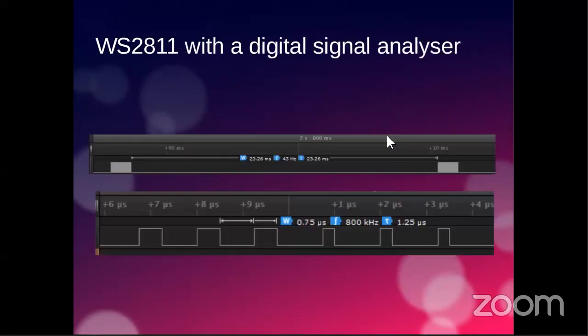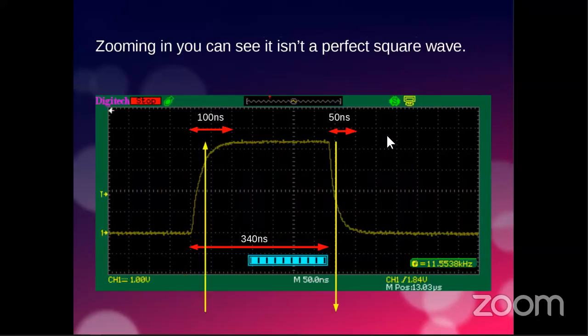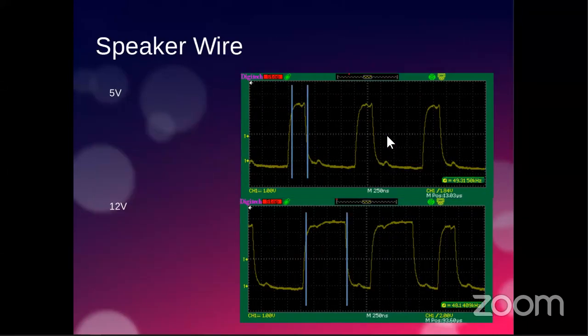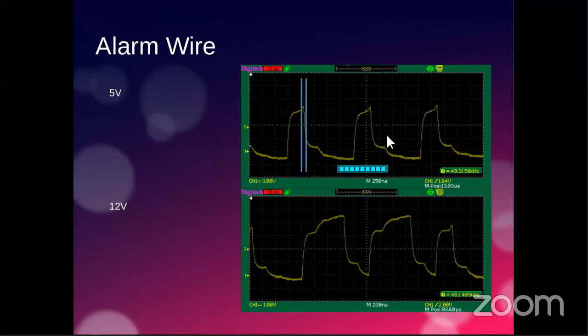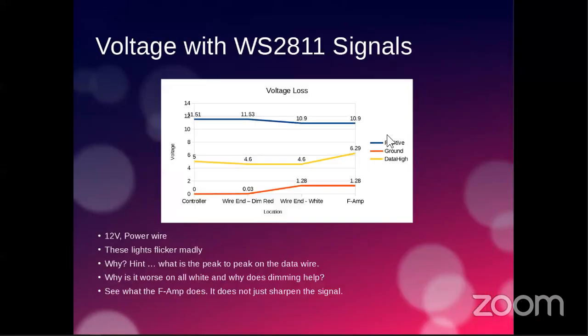if I can find it again. It's a problem with slide builds. There it is. When you do power injection, what you're doing is you're dragging the blue line up and probably the orange line down. You're not changing the yellow line at all. Okay. But by dragging the orange line down, you're increasing the difference between the yellow and the orange line. And so you may improve your signaling. Dragging the blue line up is not going to make any difference at all, to be honest.